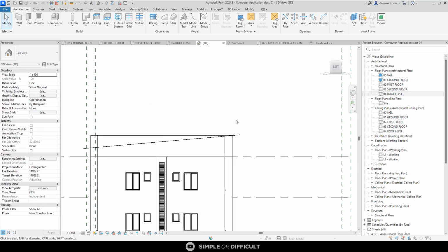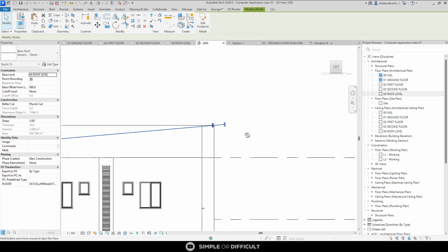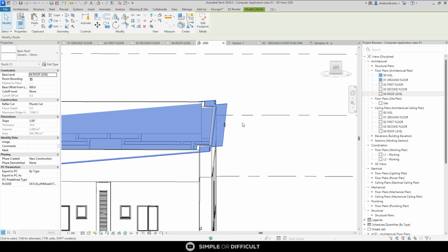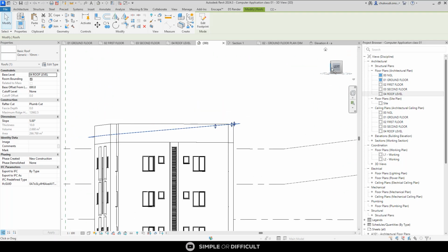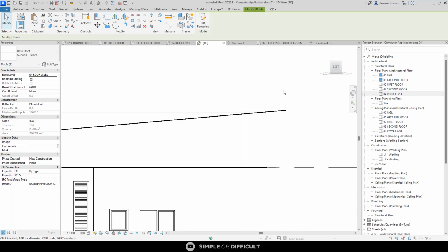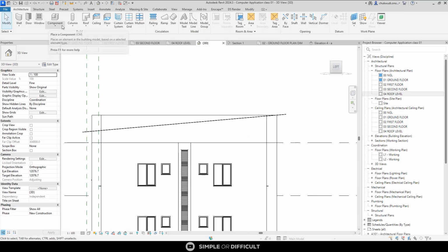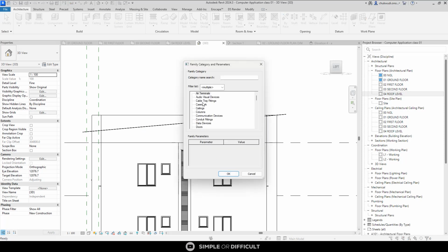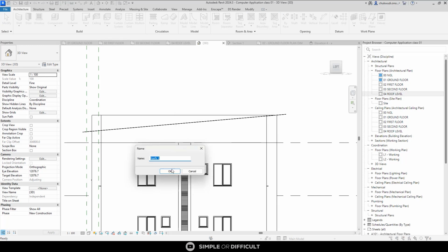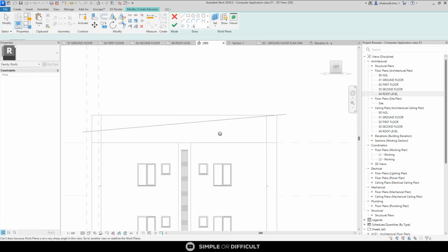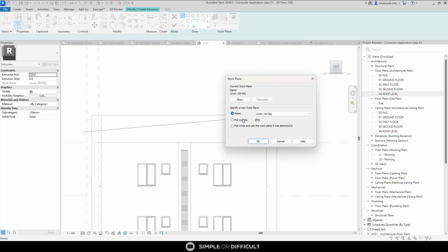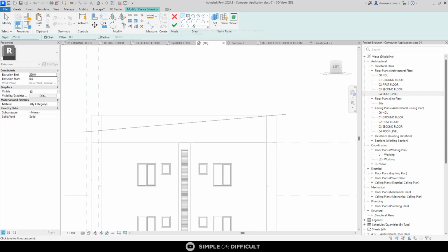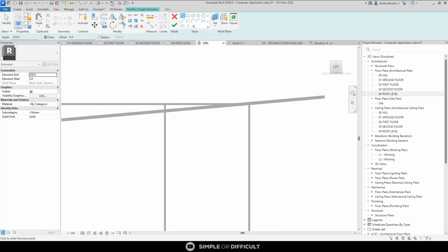So we're going to go ahead and add the fascia that's going to be underneath this roof, okay? We could have made this roof thick, like say 300 mm, and then we won't have to bother about that, but I like to do these things separately, right? So I'm going to add the fascia, and there are a lot of ways you can do this, but one of the easiest ways is with the use of model in place. So roof, select the roof inside there so that whatever you do will behave like a roof, so that I can host walls to it when the time comes. So I'm going to use this and then turn this off.